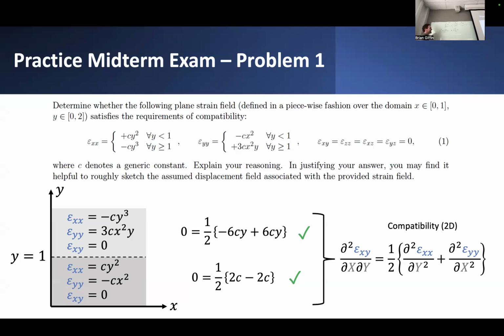All right, so if we're looking at the x displacement field, the tangential displacement field at this interface, it's the same thing, except we're integrating xx strain with respect to x, and we should then also get some arbitrary function of y. Okay, simple enough.